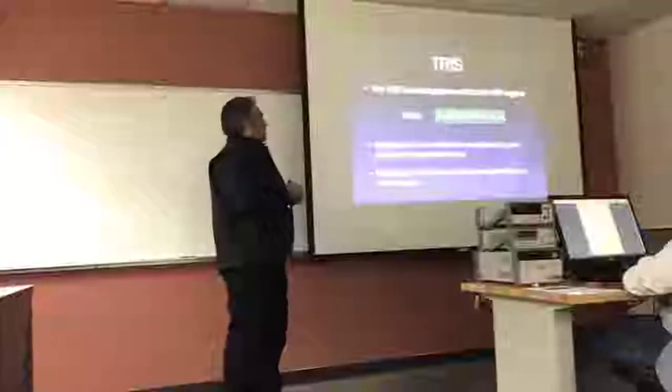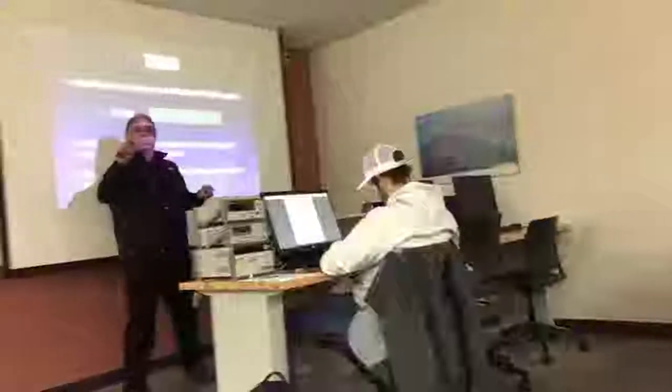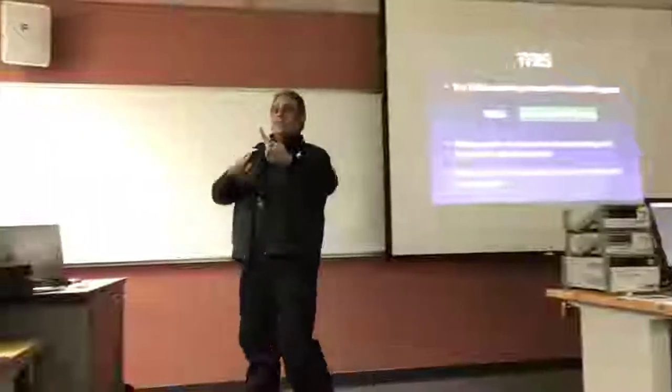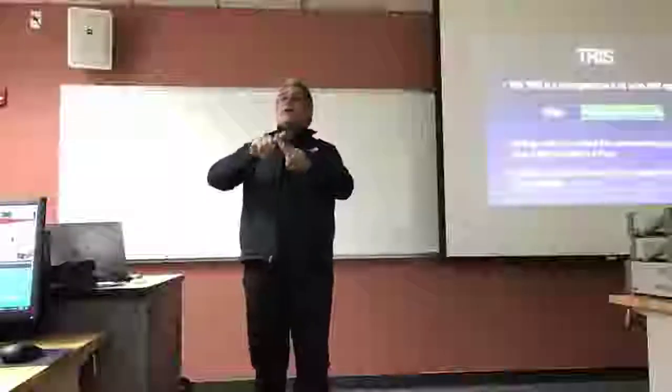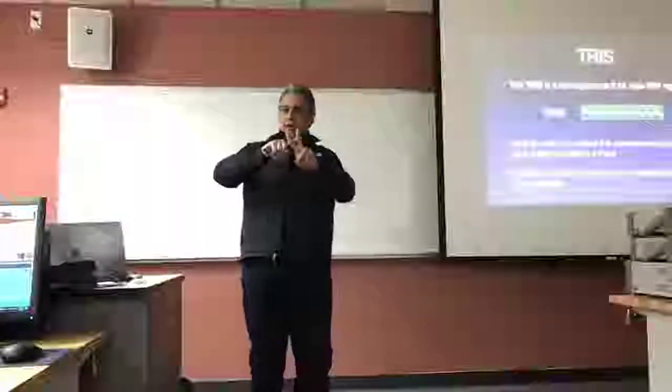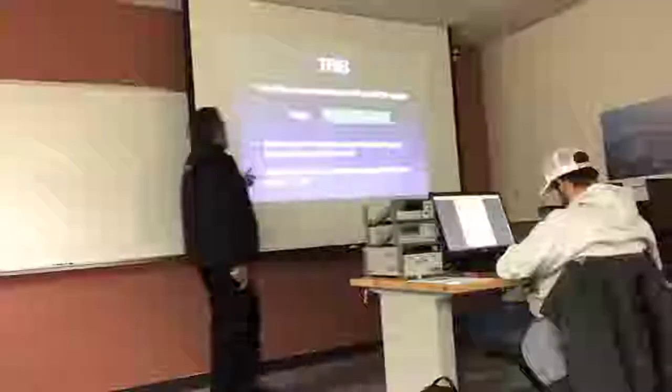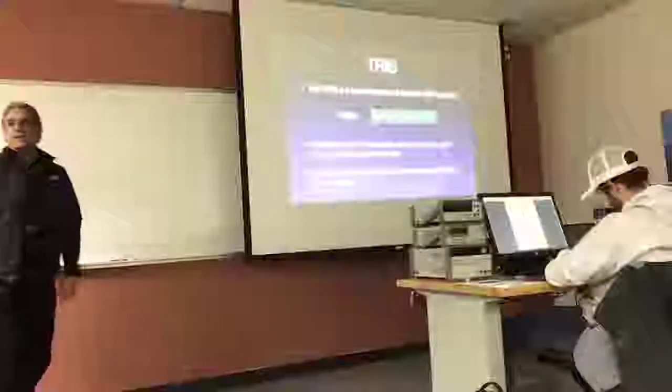All right. So one of these boxes is a single digital circuit, right? There are only two things you can do to that circuit. I can either put a 1 in it or I can put a 0 in it, all right? If you actually physically put a 1 through software, you're going to make the corresponding port pin a high impedance input.